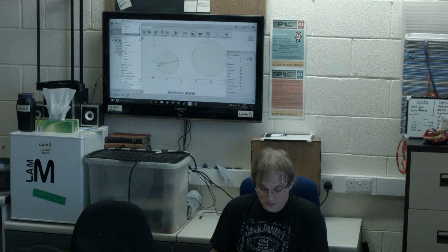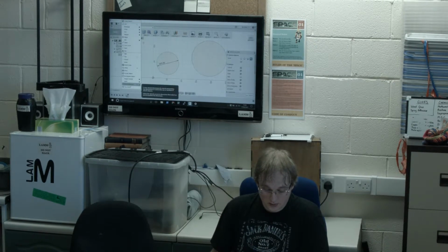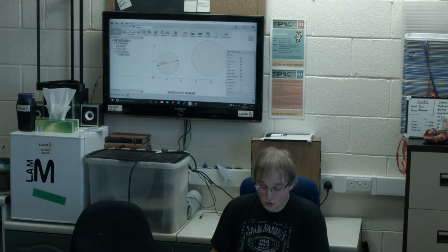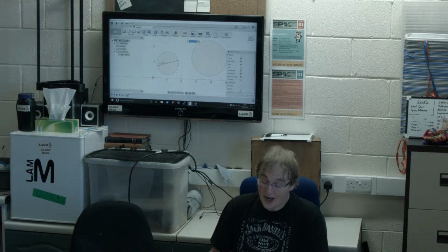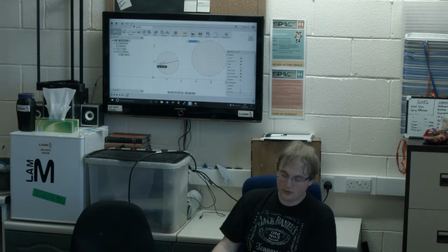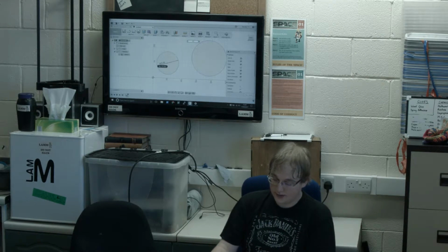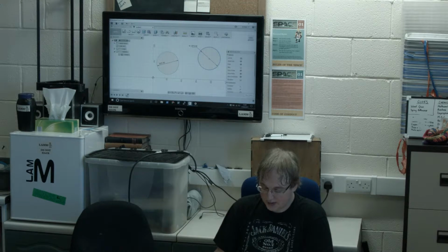In the two-dimensional sketch option, you can go to sketch dimension or press D, and then you can click that, which gives you the ability to define this dimension. Click the place where you want the actual dimension to be, and then if you click another dimension in view, it will set it to that. So now that's completely set to be that one.